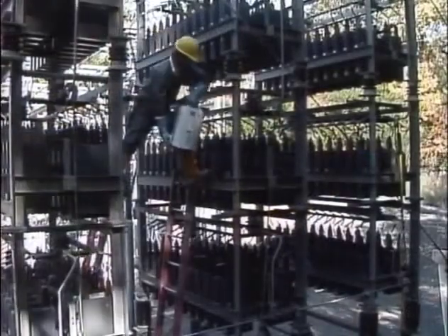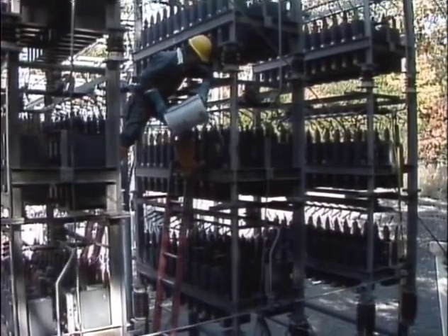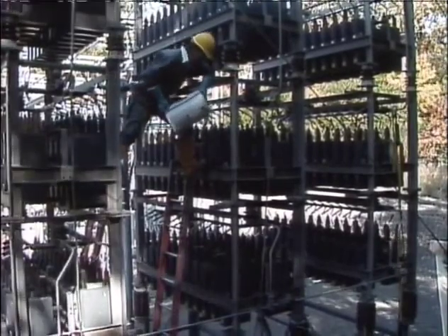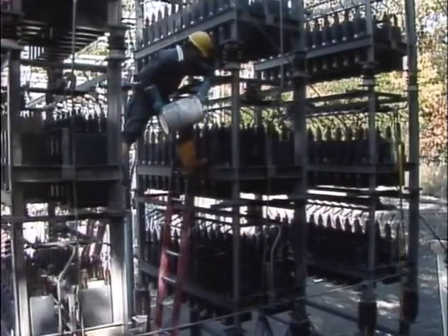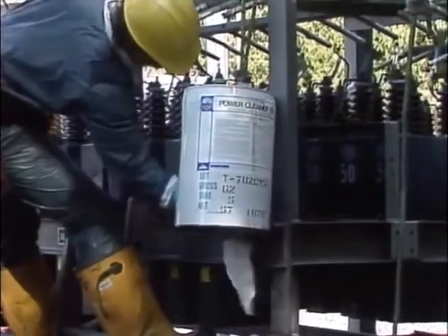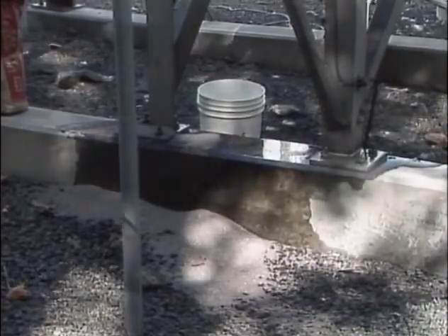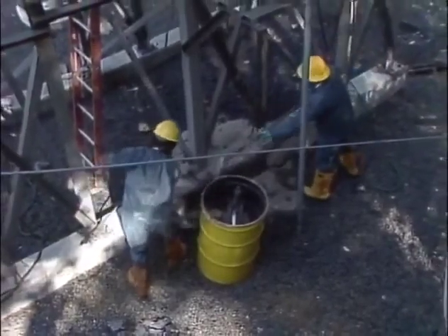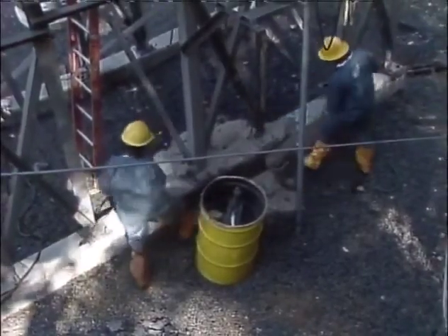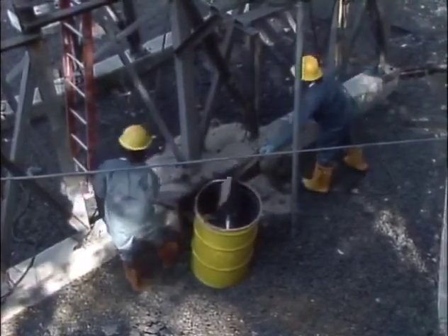Any equipment or structures that were contaminated with PCBs must be cleaned. Here, a cleaning agent is being poured over portions of a contaminated capacitor bank to rinse off PCB fluid that leaked from a bad capacitor. Then, the affected parts of the bank are thoroughly wiped down. An absorbent material is spread on the ground to absorb spilled PCB fluid. The absorbent material and the contaminated soil are dug up and placed in an approved container. When the cleanup is completed, all contaminated clothing and rags are also disposed of as required.